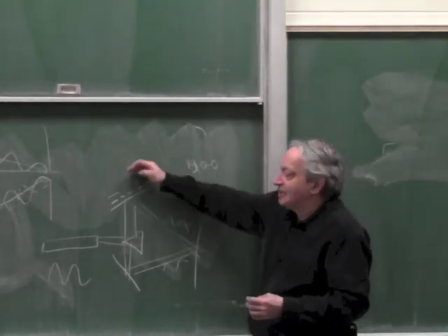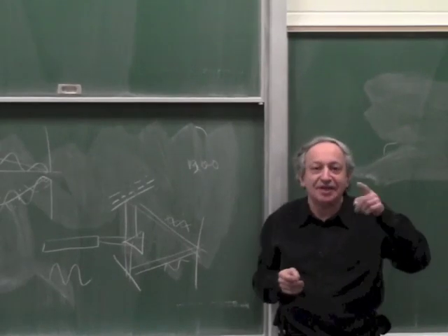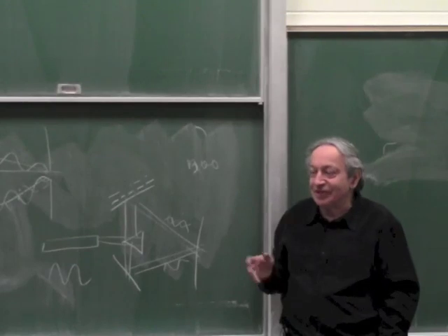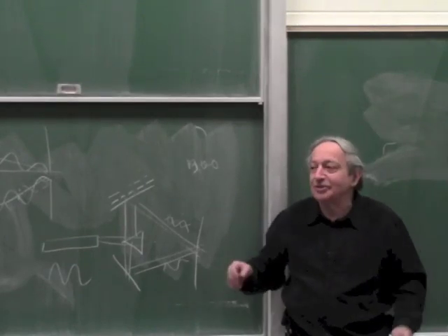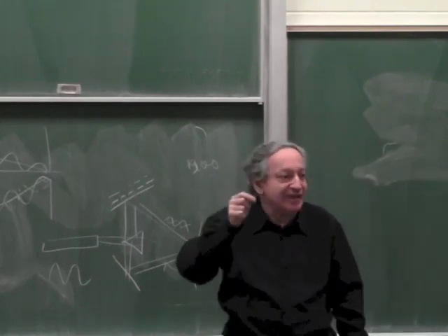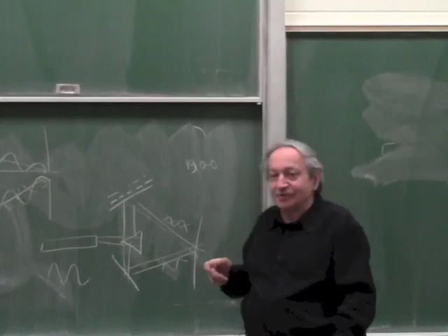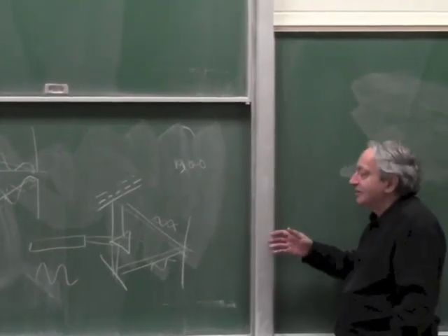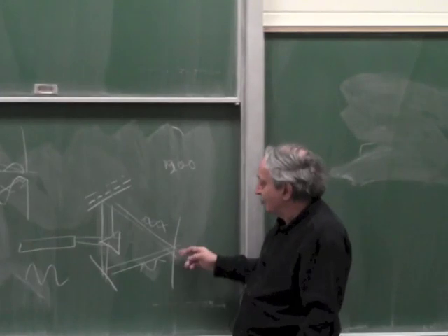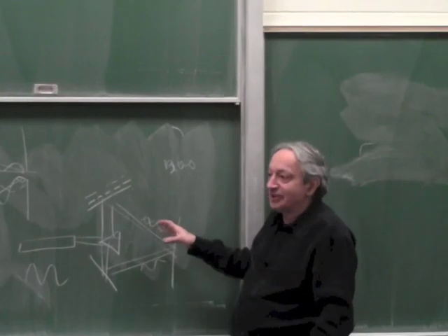But when I move this, instead of actual lines, I'm using the wavelengths of light as lines. That has huge advantages, because the wavelength of light is stable, you can make a long encoder, it's very fine. It's very difficult to scribe lines as dense as the wavelengths of light. So that is a perfect encoder. If I can move that, okay, I can measure very small movements to great precision, and that's called an interferometer.